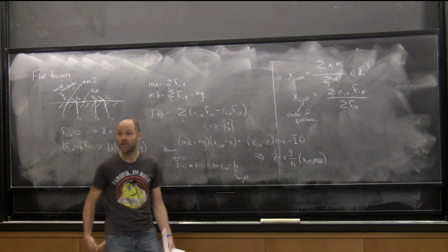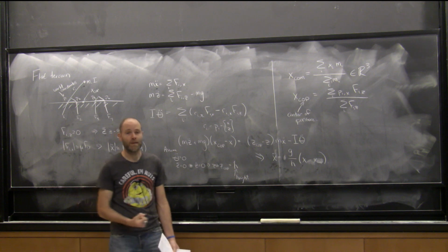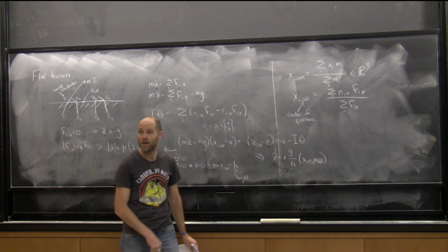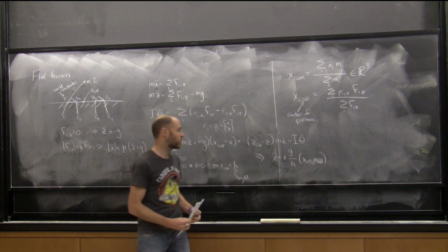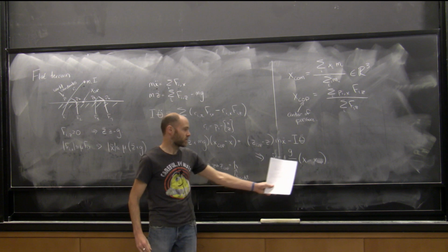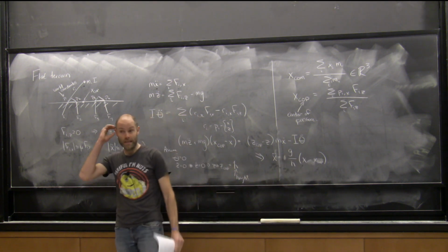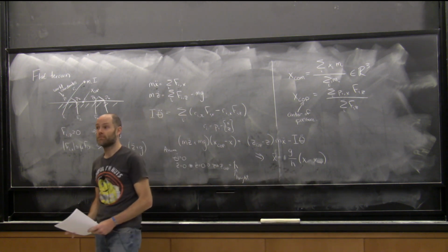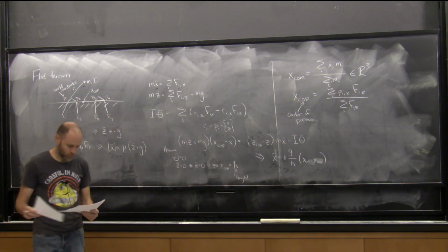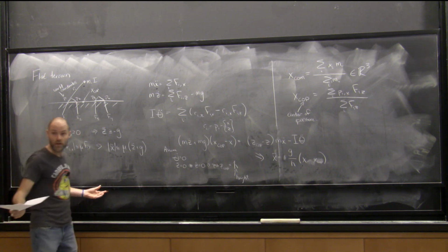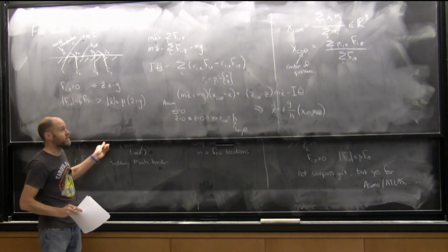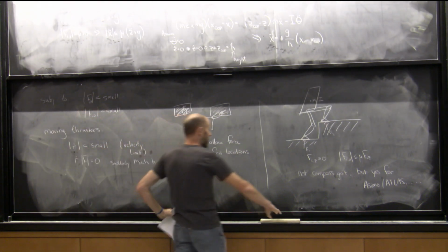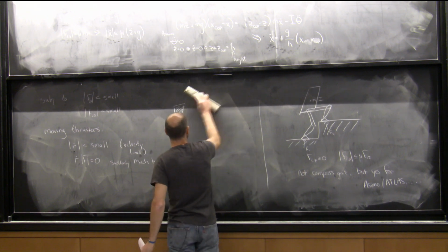And by regulating the acceleration of the center of mass, it's got to be controlling its center of pressure, at least. Maybe not the details of the force, but the relevant force. Okay? So the center of mass trajectory and the center of pressure trajectory are linked. And in the flat ground case, it's a linear relationship. Okay, so yeah, does that make sense? It took me a really long time to appreciate how important that was. But it changes a lot of things.